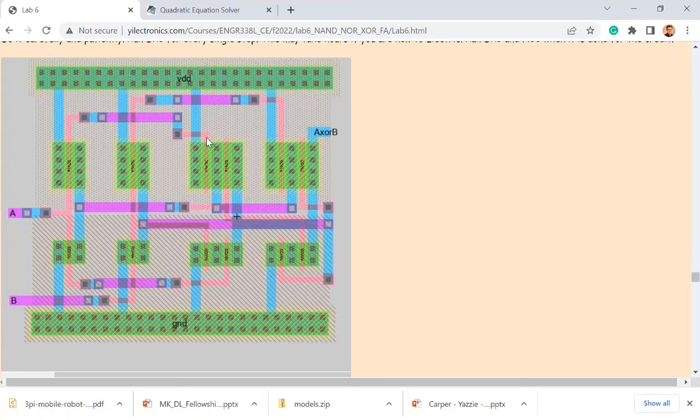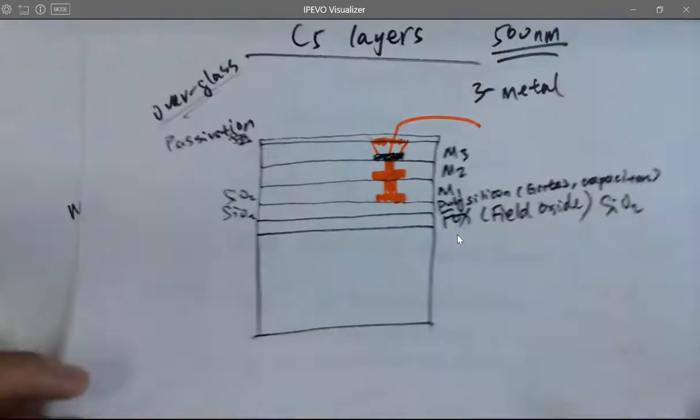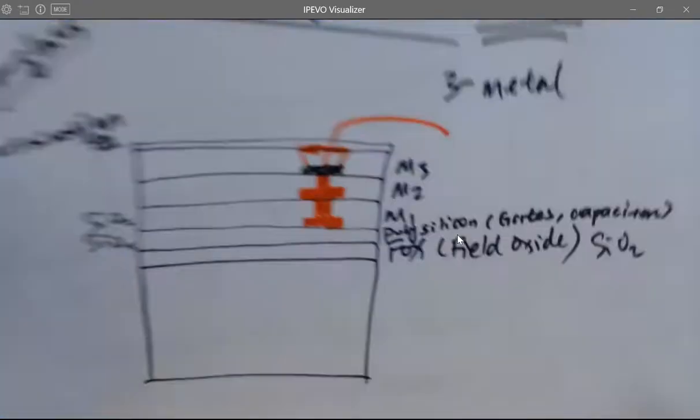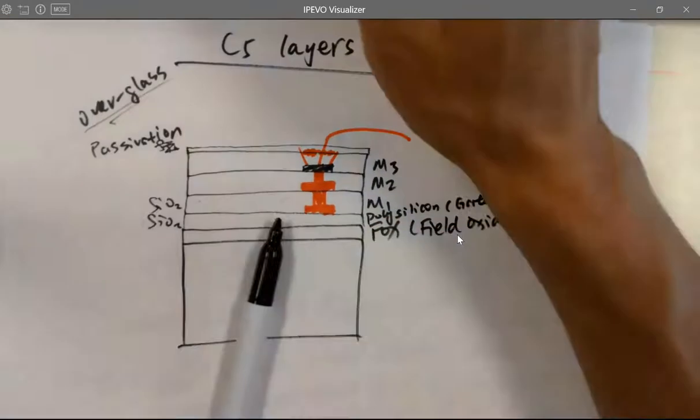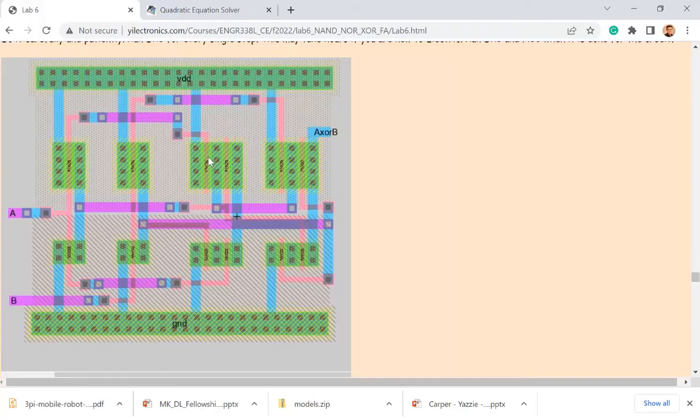Yeah. So you want to avoid long polysilicon wires, because I just said the resistivity, the sheet resistance for poly is how much? 200. What about metal? 0.1 ohms, right? So it's a lot less, a lot smaller. Like you have that long one on the left. This one? Yeah, like why wouldn't you just go straight up to metal?